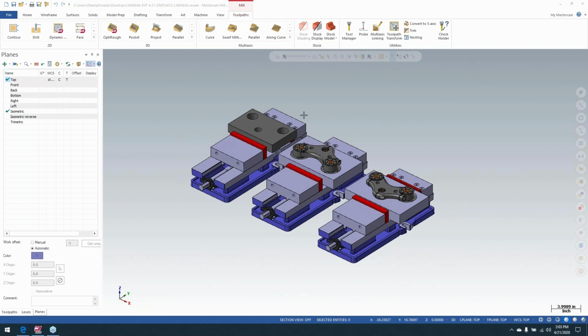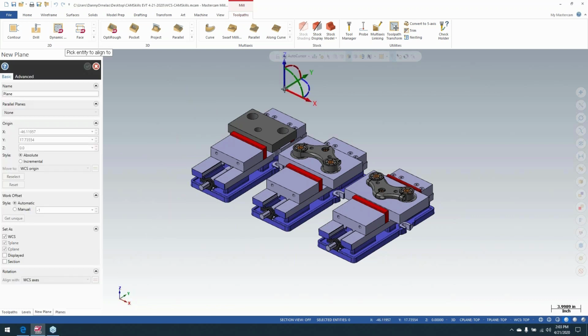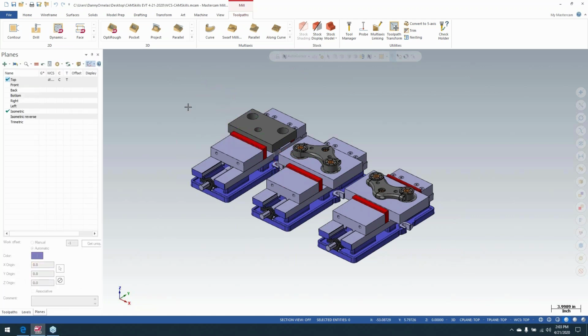So I'm going to start off real simple. In the latest versions of Mastercam, we can use this icon. Here's the gnomon in here, and we can move it around and place it where we want to. But I'm going to go back a bit. Here within the panel, to create a plane, we have a few extra options, and some of these are just legacy options. Most of them, first things first, from geometry. Let's go ahead and spend a few minutes, and we'll cover this here.